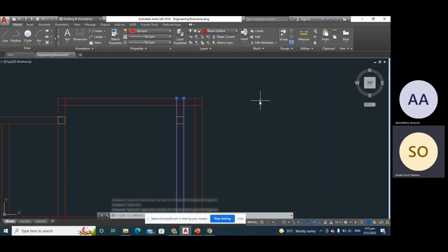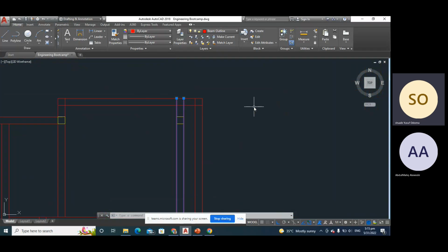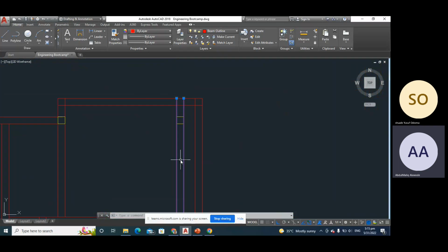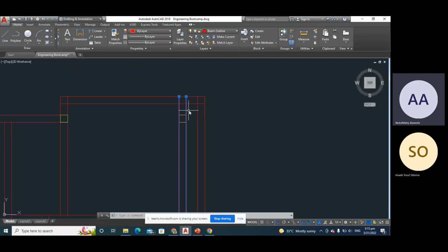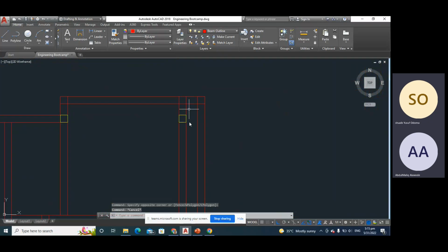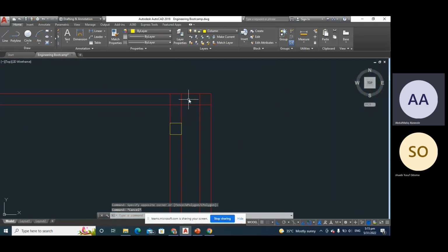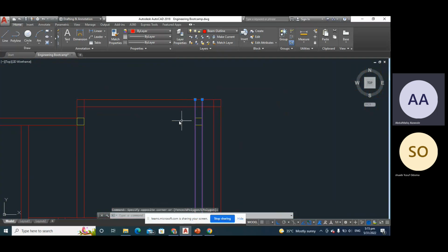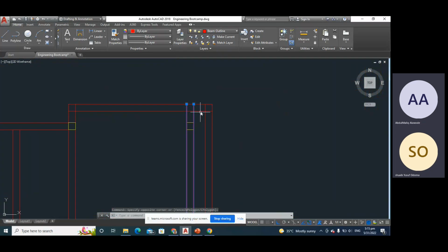Yes, at that junction it is appearing as a cantilever, and the beams there are supporting the slab. Okay, so it's acting as a cantilever, agreed. But what is it supporting? The beams are the ones supporting it, the slab. Yeah, the beams are supporting the slab. But what I want to hear, I've not heard it. At this junction that my cursor is going around, there is something going on there. Which one is the primary beam? Which one is the secondary beam? The secondary beam is the horizontal beam, as it's being supported by the long vertical beam there.